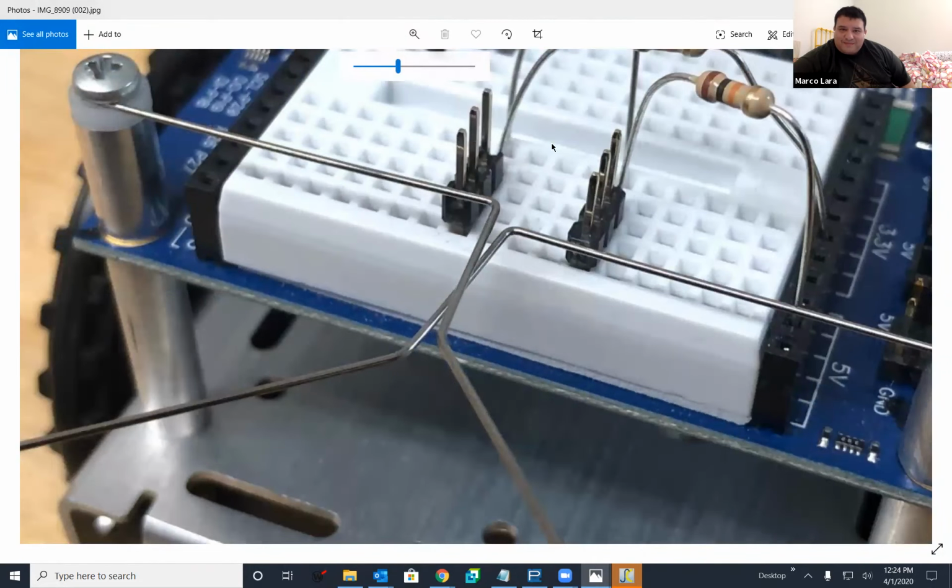Because the tutorial has us going in on the 3.3 volt on the left-hand side. Gotcha. And yours is going into the right-hand side. I don't know if that really makes a difference or not. Well, really, you should be on 3.3 volts so you don't damage the I/O pins. But fortunately, the 10K resistors are large enough that the I/O pins are still protected. It's okay in this case, but there are other cases where it wouldn't be.